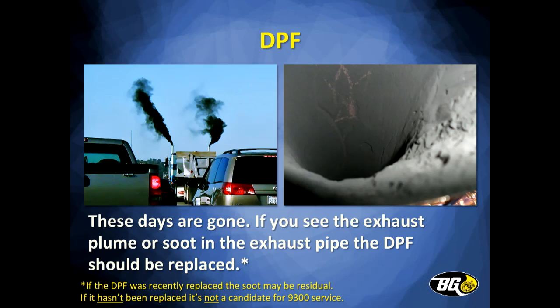If you see a tailpipe that looks like that, that's not a candidate. There's something wrong with the DPF. That DPF needs to be replaced. Or maybe it was already replaced, they just didn't have a chance to clean the exhaust out.